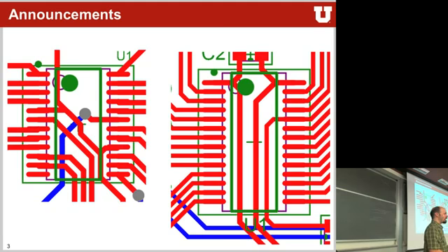Exactly. And even if you route to the pad, if you hit spacebar, it actually changes the angle at which it goes into the pad. Sometimes you are at a 45-degree angle and you hit spacebar and it actually aligns it properly. But yes, oftentimes for pads in Altium, it's easier to route away from them than into them. So what I oftentimes do is I route out of a pad, go close to the other pad, stop at the location where I wanted to, go to the other pad and finish it that way around. But then yes, again, hitting spacebar helps you a lot in aligning and getting the right angle into it.